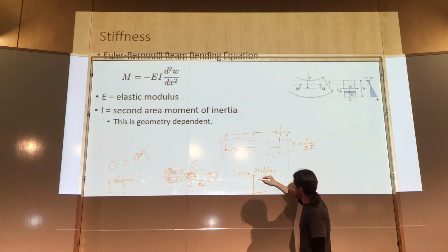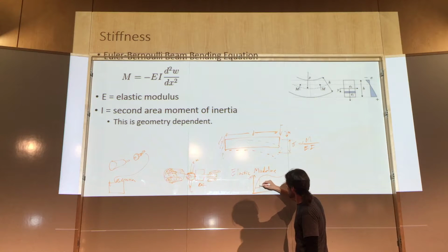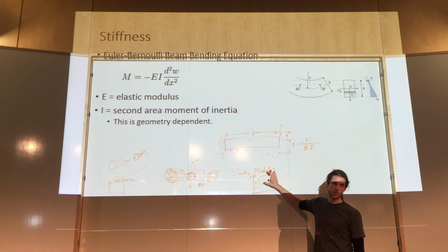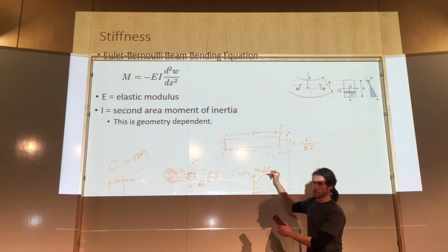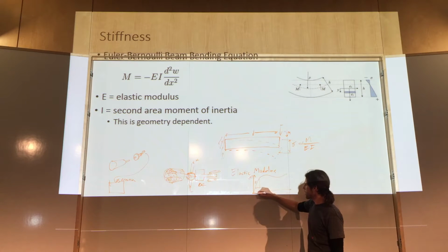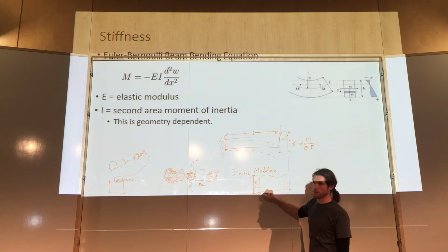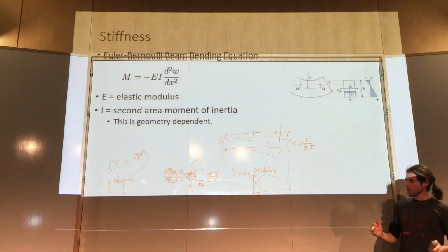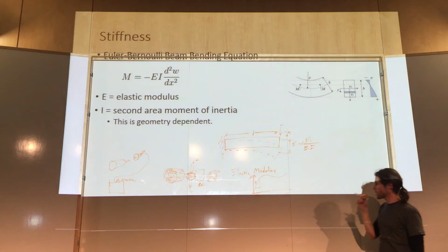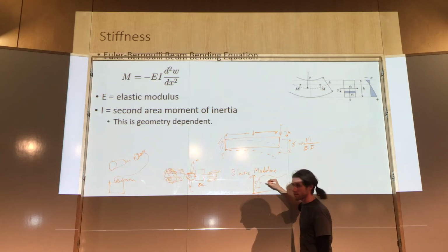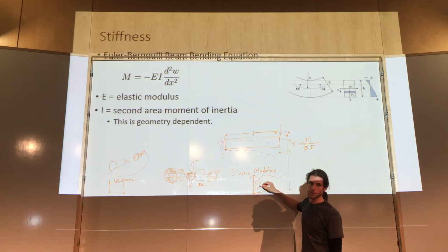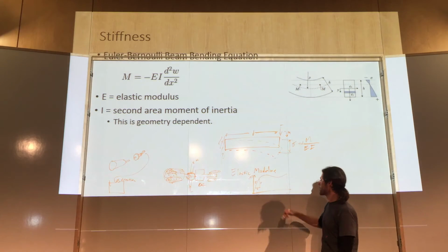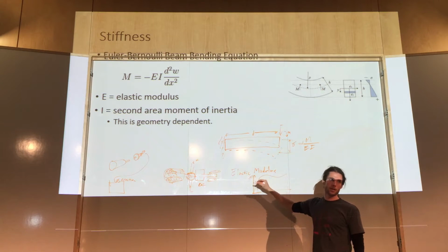And there's this linear zone, which is the elastic region of your material, defined as how much load you can apply and, when you release it, come back to within, I think, 0.02% of your original dimensions. There's a certain amount of stress you can apply, and a certain amount of elongation during that elastic stretching. And the ratio of those is E, your elastic modulus.